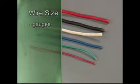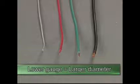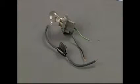In addition to color, wires are identified by their diameter. Wire diameters are graded in gauges on some vehicles, or the diameter of the wire is shown in millimeters on other vehicles. The lower the gauge of a wire, the larger the diameter. The larger the diameter of the wire, the less resistance to current flow. For example, the wire to a fusible link may be a thicker diameter 8-gauge wire, while a lamp bulb would have a smaller diameter 14-gauge wire carrying current to the bulb.